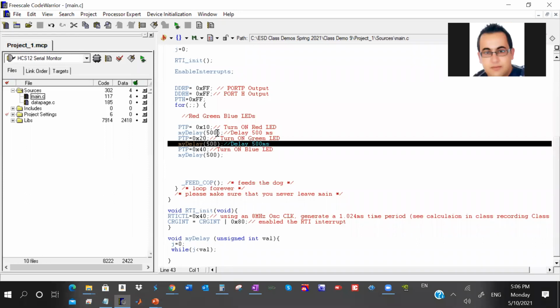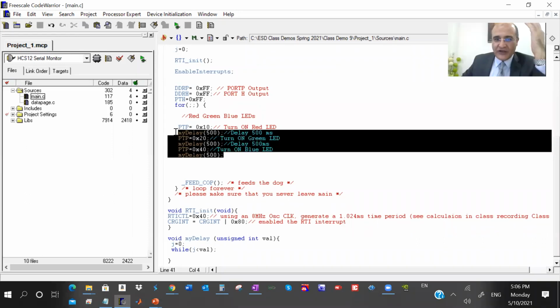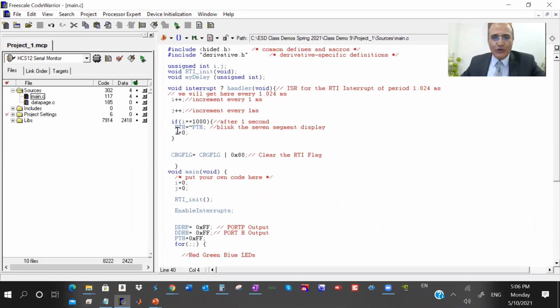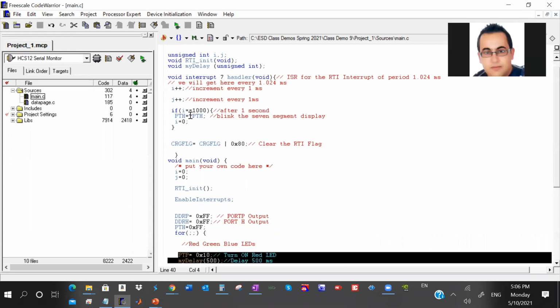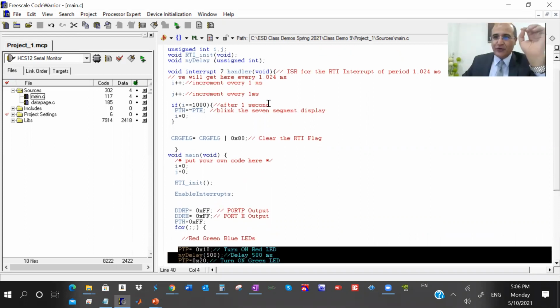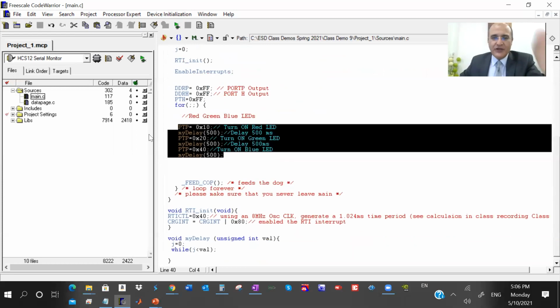Of course, Mustafa, we can make an empty loop. We can cut this thing and write the whole thing inside the interrupt service routine. But you cannot vary the amount of delay in this case. Anyways, you can always have your code in a periodic interrupt service routine. Every 10 milliseconds, go do all these things. Then do nothing in the main loop, just go sleep, for example, to save power. Wake up every 10 milliseconds. Do something for 1 millisecond, then sleep for 9 milliseconds.